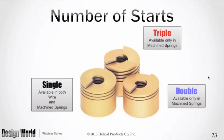Okay. Now, on the subject of multiple starts, here's what they really look like if you were to cut them open. You can see the single start on the left and the double start on the right and the triple start in the back. From a cost standpoint, it's make the spring once, make the spring twice, or make the spring 3 times. So it does have some costs associated, but it does things that you can't really get with a single start.